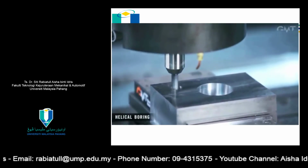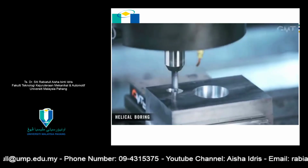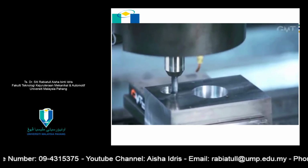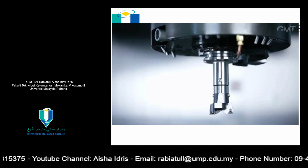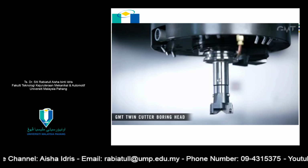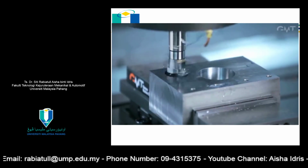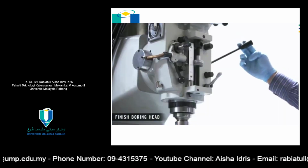Helical boring with an end mill is an economical way of creating larger holes. Deeper holes can be made using a boring head. The adjustable twin cutter unit shown here is used to enlarge pre-drilled holes. A finish boring head holds a single adjustable cutting edge for the highest precision and the smoothest finish.